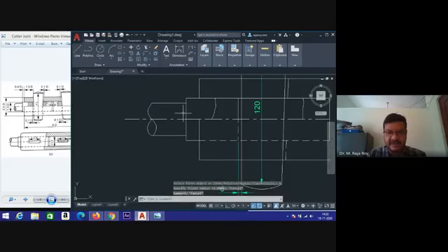You just check the distance here. Distance is 4.5. So 5 fillet is not possible. We can go for 4 fillet. Take the fillet command. Go to radius, enter the distance. Fillet radius is 4. Now you select here and here. You can get fillet like this.